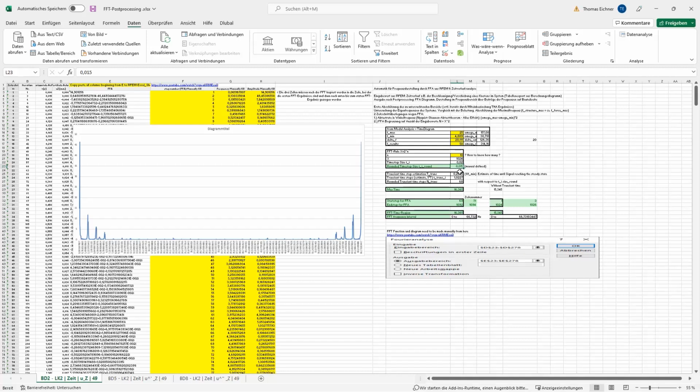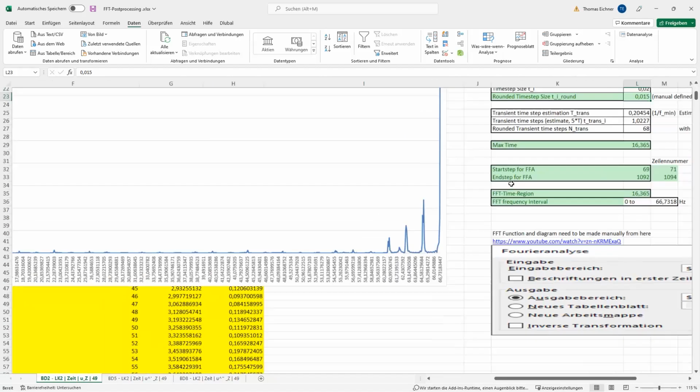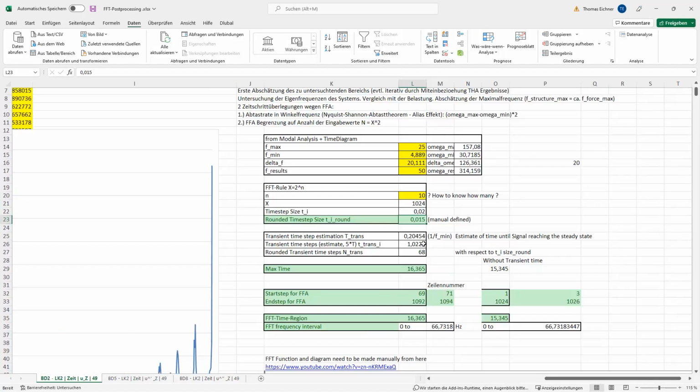And with that, I defined we will take a 0.015 second time step. Oh, I'm sorry, I will go a bit closer here. So we will go with this 0.015 seconds time step, and we don't care about initial swings or the first few seconds, since they always have some strange results, I would say. But we will just ignore this, and we will take this into account anyway.